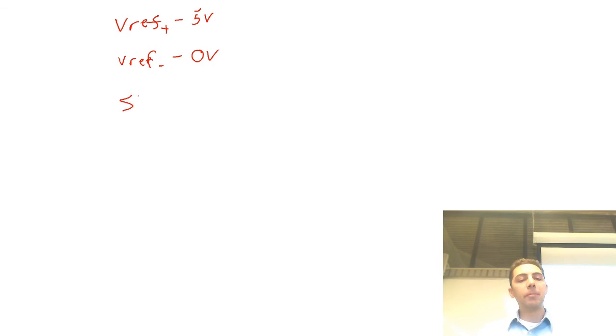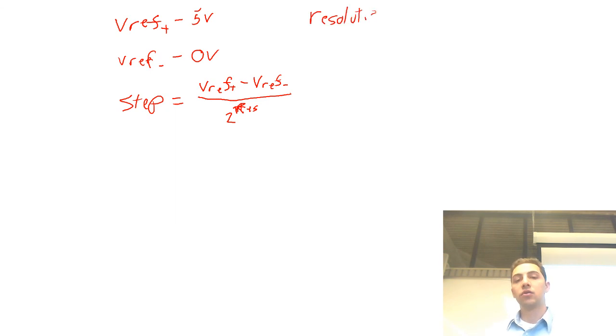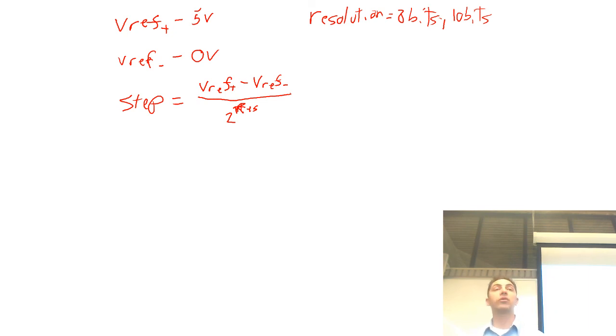If I wanted to know my step size, because that's one of those things we need, step is 2 to the resolution. So resolution would be something like 8 bits or 10 bits. Yep. Is the ADC value signed? No, because it is referenced to ground. In the ATmega32, we can actually get signed numbers because we can do differential measurements, but not in the 328p.